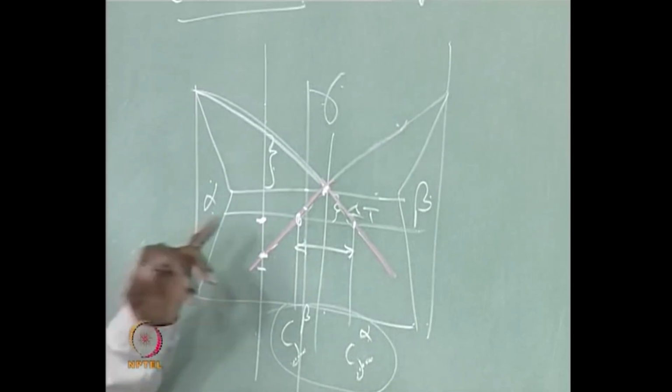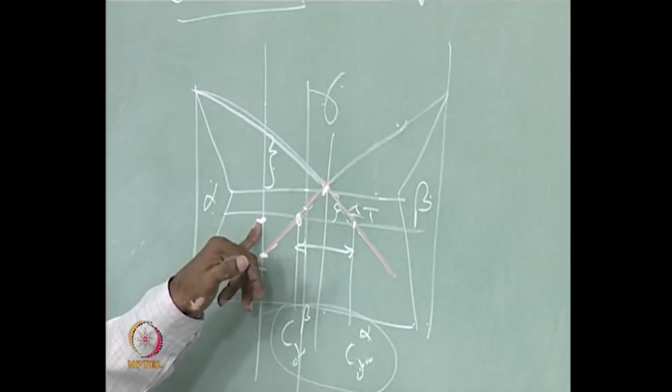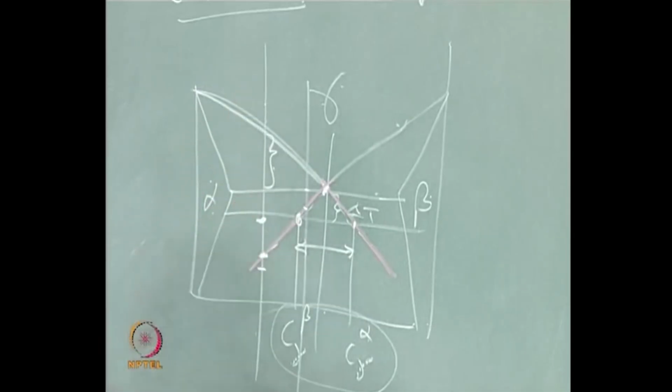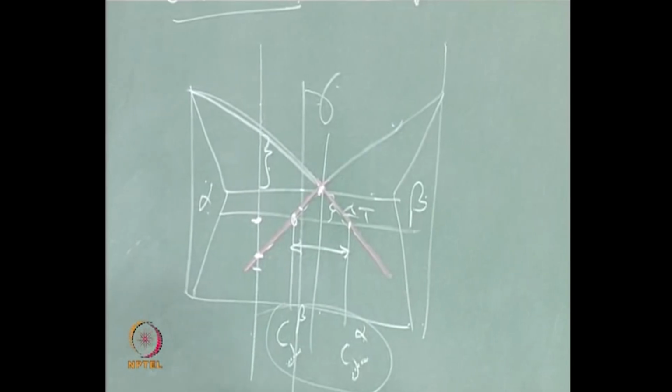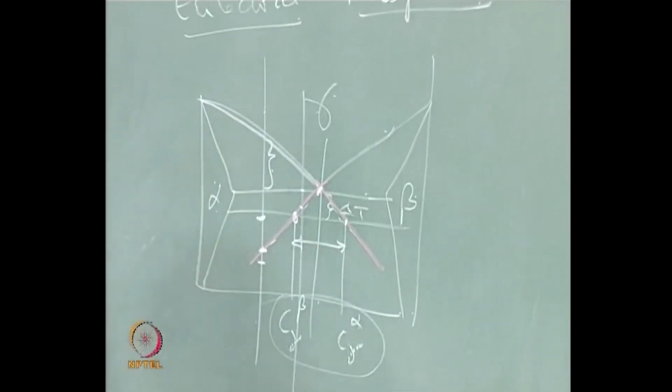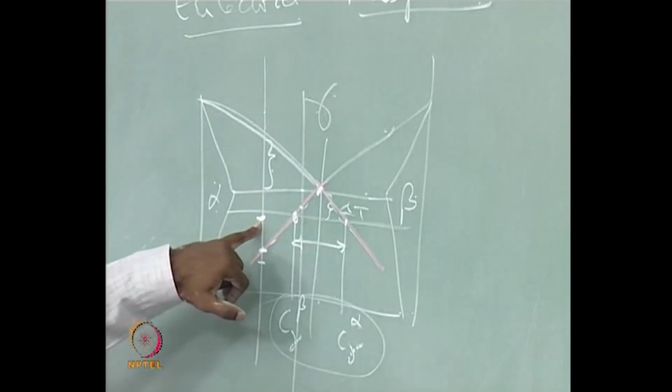So you will have an alpha forming even if you have undercooled it below the eutectoid temperature, not simply cooled it. If you have simply cooled it, by that time eutectoid transformation is already over. So if you undercool it to that temperature, you can still get alpha.